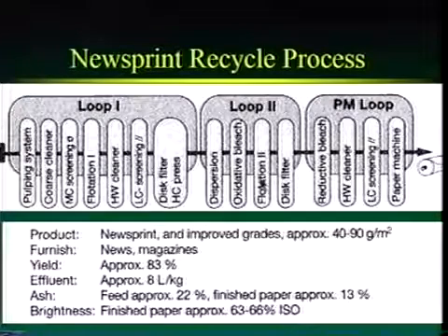So we do flotation, de-inking again, and that follows the rule I talked about: we want to repeat inefficient operations. Then we go to a disc filter, thicken it up a bit, and go into the paper machine loop. Because in this case the reductive bleach is compatible with the paper machine water, we'll do our reductive bleaching here.